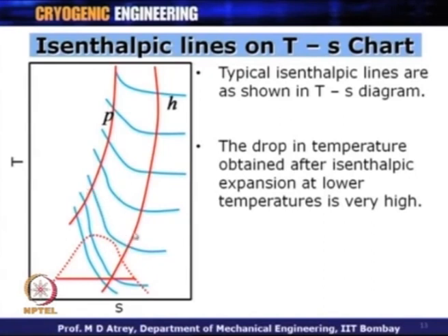I am going to get more and more real gas expansion, and in this case, I am getting very large cooling when expanded isenthalpically. All right. One should always have isenthalpic expansion when one goes away from ideal gas, and the best way to go away from ideal gas is to have liquid. Liquid is nothing but completely away from ideality.